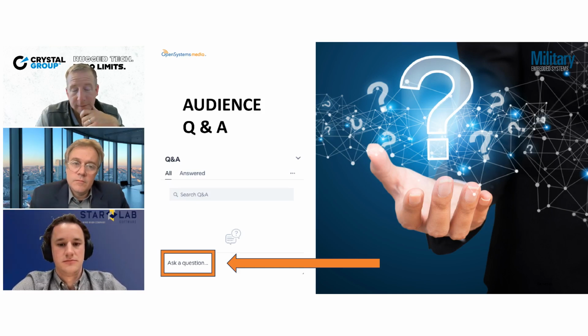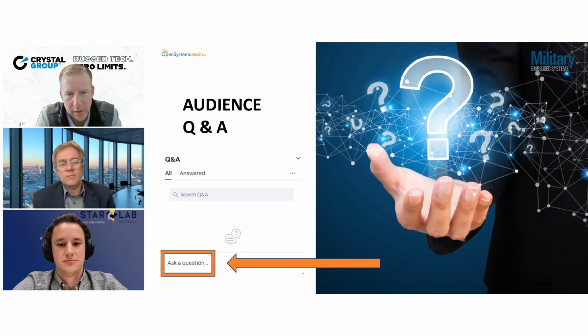So don't have two different systems, meaning thermal management and structural. So it's literally the same system, because we just don't have the volume. We don't have the size, weight, and or power to go have two separate systems to manage those two separate things. So a lot of what we do is integrate thermal management and structure. So you use the structure to do the shock and vibe, but you also use it to help move the heat away from the devices to the parts of the box where you can actually then pull it away from the actual box and dissipate it, make it somebody else's problem at that point.